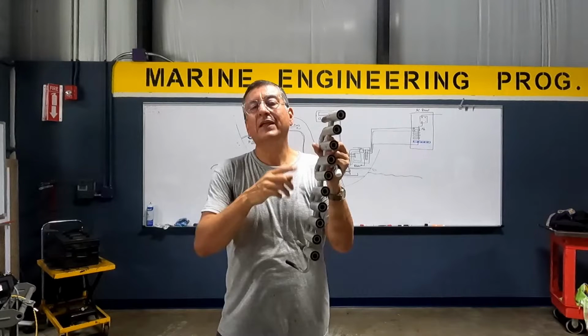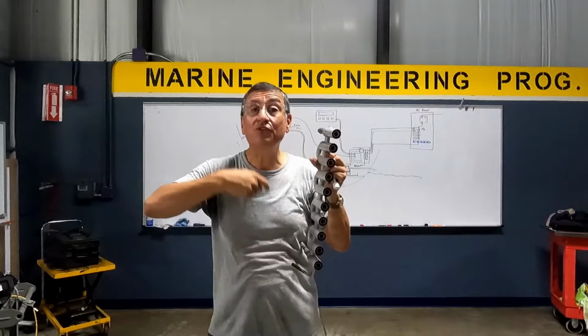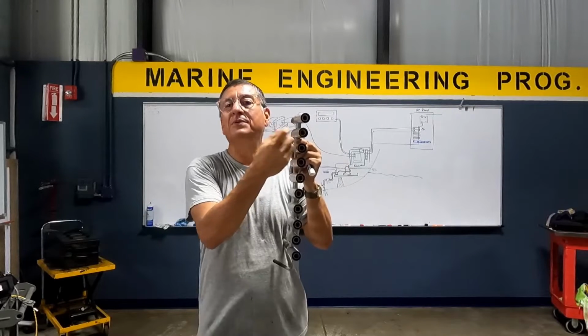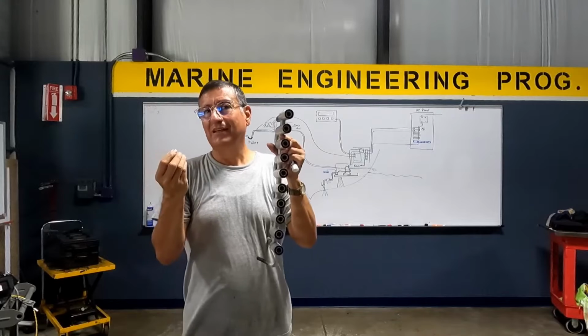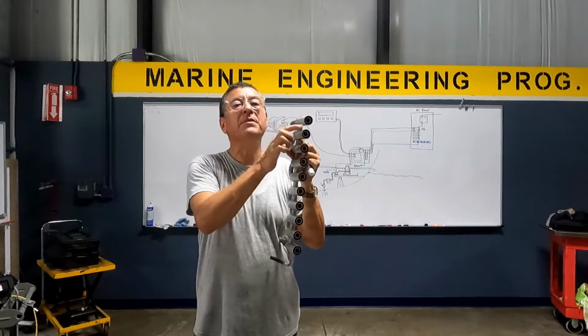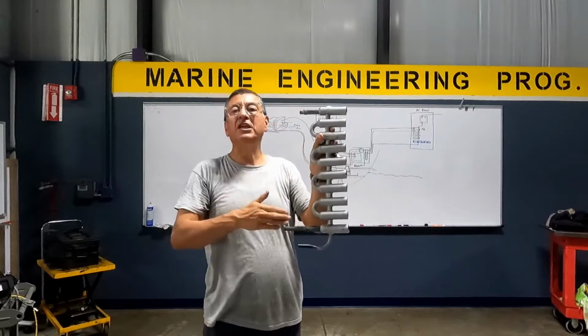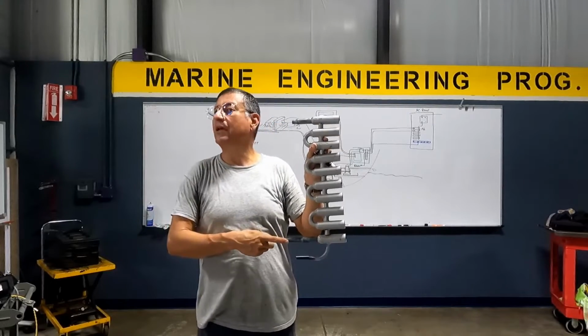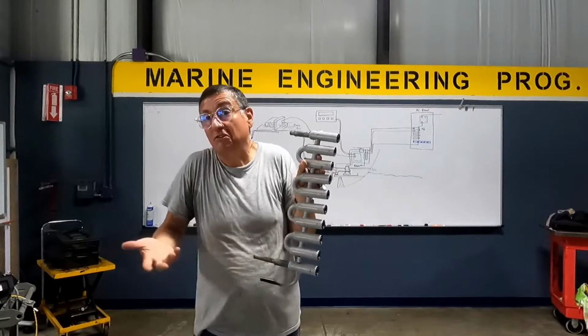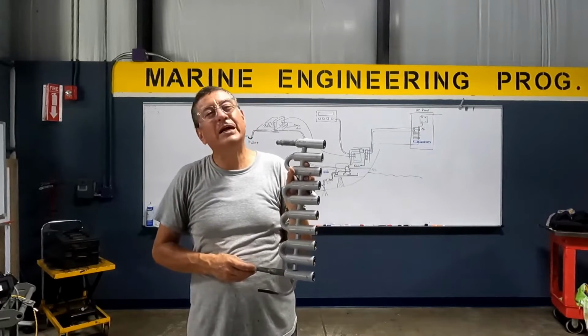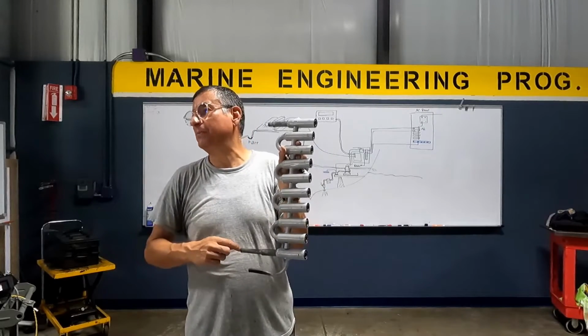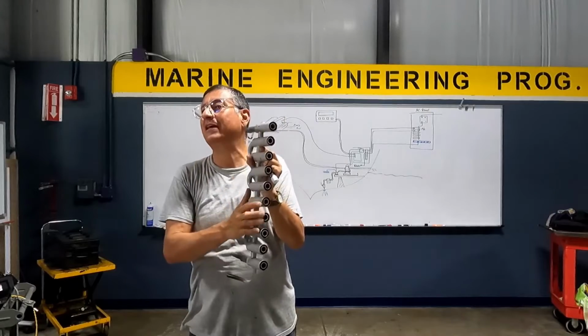If the air conditioning unit is not used frequently, the salt water in between both pipes creates calcium and reduces the heat transfer in between both pipes. For that reason, periodically, once per year, you need to flush this one with water and bleach, for example, or water and other product that is special to remove that calcium in that area.